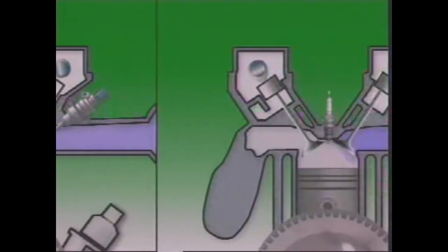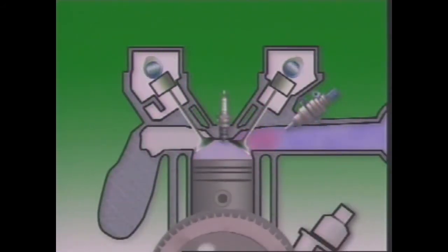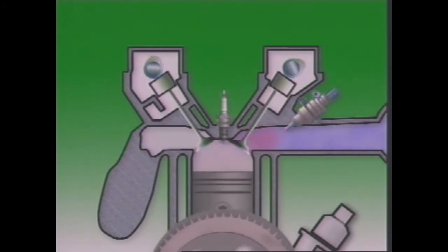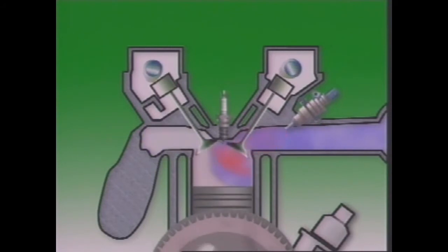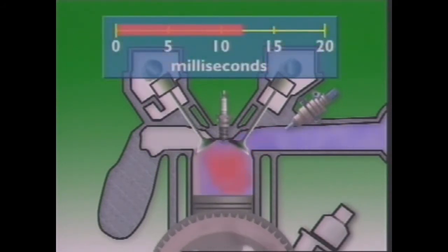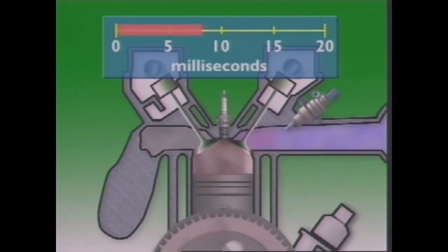In some cases, during engine cranking, extra injection pulses in each revolution can provide the extra fuel. It depends on engine temperature, and there is a time limit to prevent flooding. The cranking period is followed by an after-start enrichment. Over about 30 seconds, this slowly reduces to normal warm-up. The engine then responds steadily immediately after releasing the starter.